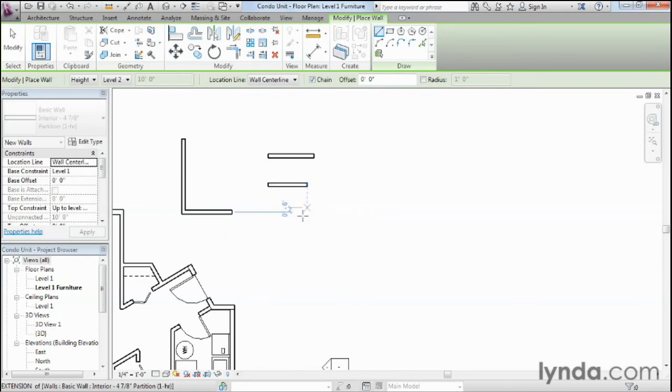Let's press escape again. Now, when you want to do just inches, you can either do the inch symbol to make it clear to Revit that this time you mean 10 inches, not 10 feet, or using that same method I just showed you a moment ago, you could do 0 space 6, for example. And now I've got a wall that's exactly 6 inches long.